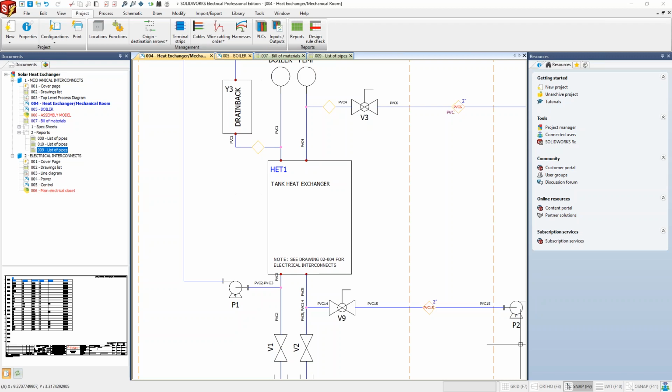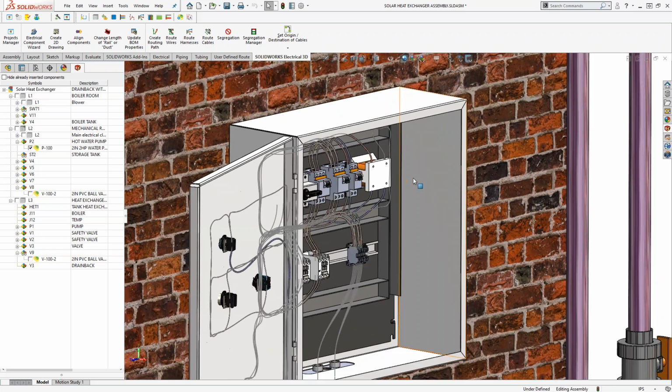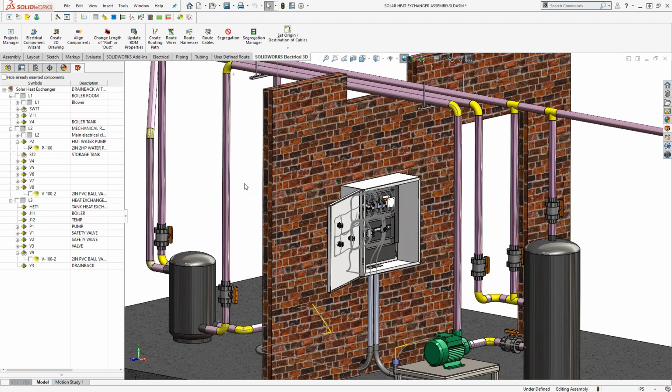And that's where you make the parts electrically intelligent inside of the model. Those connection points, C points that you might see in the routing library manager, are built in as features into the feature tree of that part. So once you put them in, you never have to touch them again. They're saved to the part. So if you have this very specific manufacturer part, you won't ever have to touch them, which is nice. As far as the mechanical information on the electrical side, it depends on how you have that.